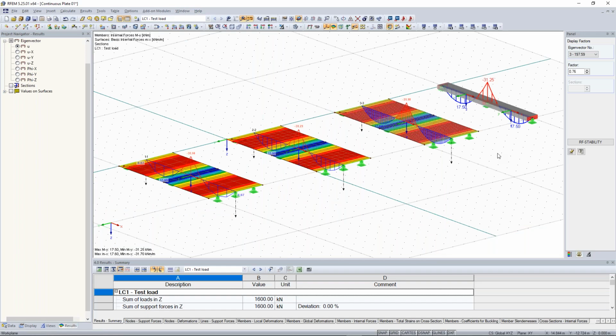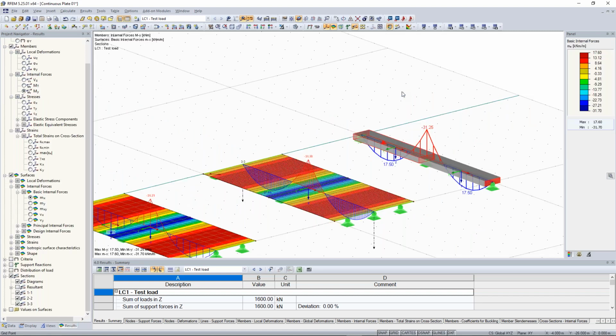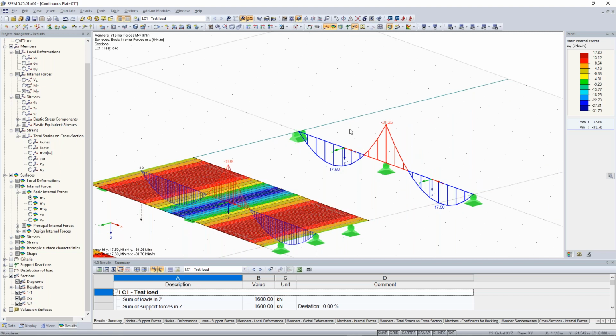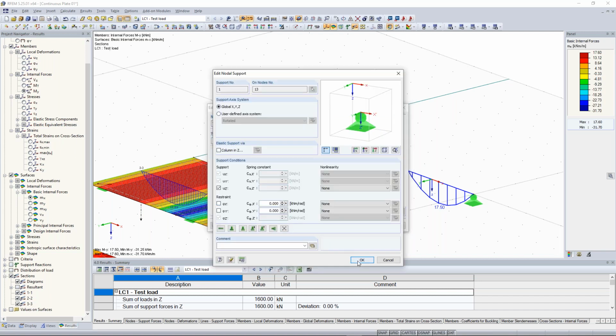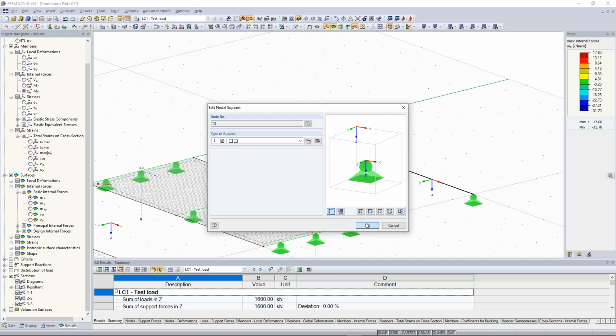And there was one question, why we need Vz for the beam hinge in the previous example. I think you mean this one, this nodal support. I can tell you why. Because when we calculate this like that, then the beam would rotate over its own axis. So this would cause an instability. I can show it to you, and therefore we have to close this directional deformation. Otherwise, it won't be possible to calculate it.